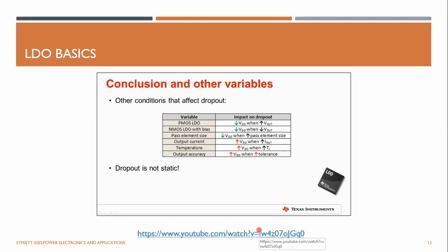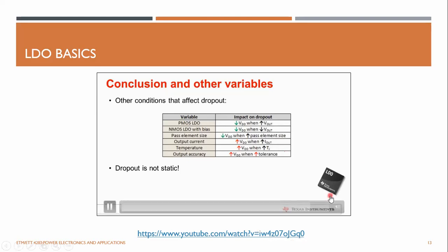When designing your circuit, be sure to keep an eye out for the conditions in the table and keep track of the input voltage variance. Any changes there could potentially change how the LDO regulates.